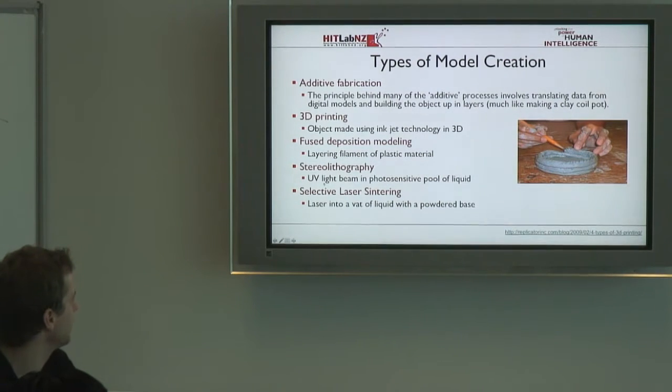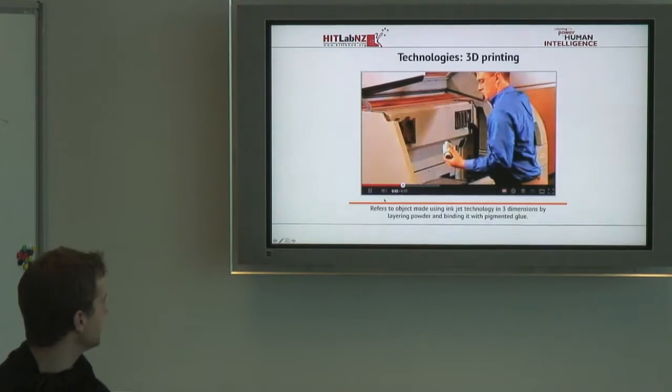But certainly these 3 down the bottom here: fused deposition modeling, stereolithography, and selective laser sintering. These are the 3 that you're likely to see. This is the definition that I give when I'm describing what 3D printing is, because this basically includes all of these really, but these are the 3 that if you go out and buy a 3D printer, it will most likely do one of these 3 things. So we'll talk about them in a little bit more detail now.